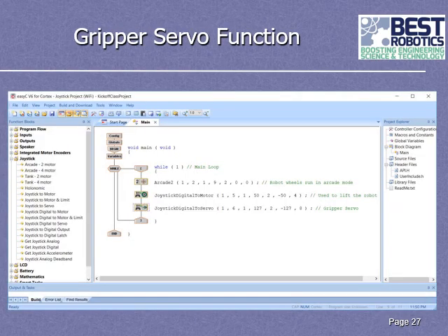So now you have completed all the software you need to run a simple robot. This code will allow you to move the robot around in arcade mode. It will allow you to raise and lower an arm, and it will allow you to open and close a servo. Now, if you decide you want to have 2 servos in your gripper, or if you want to add another motor, you would add either a second servo or a second motor, and you would do it exactly the same way as we did the previous ones. Again, you'd have to pick a port that's open and pick some buttons that haven't been used yet, but it's the exact same process to add more of those in here.